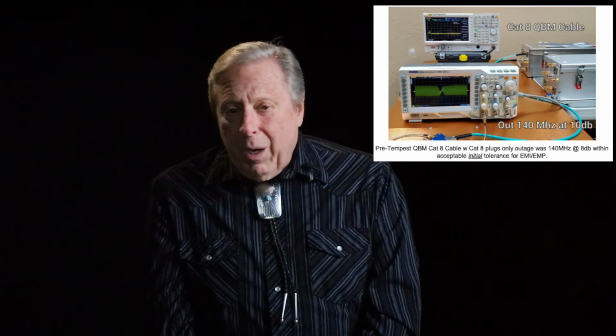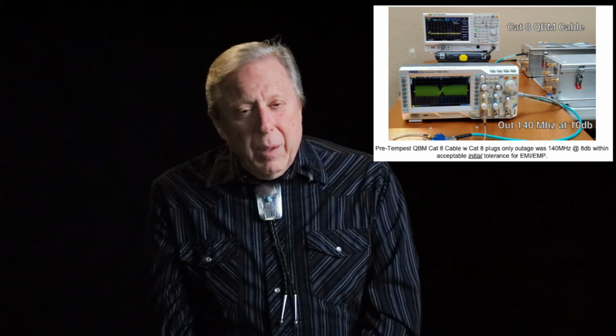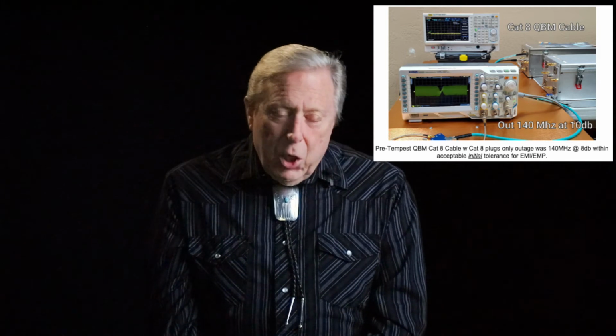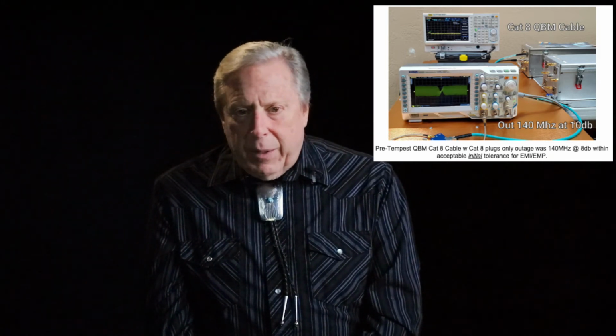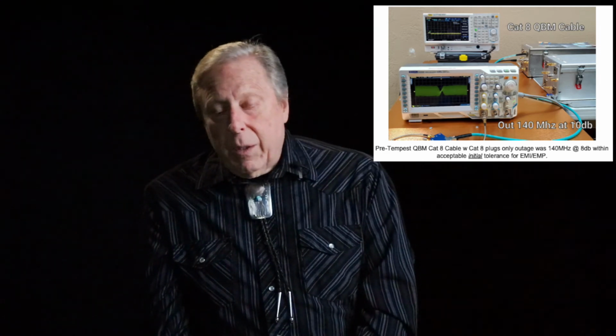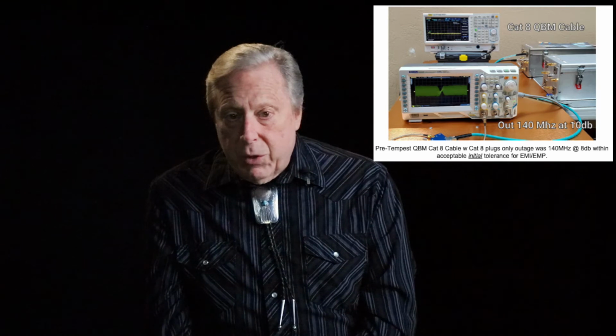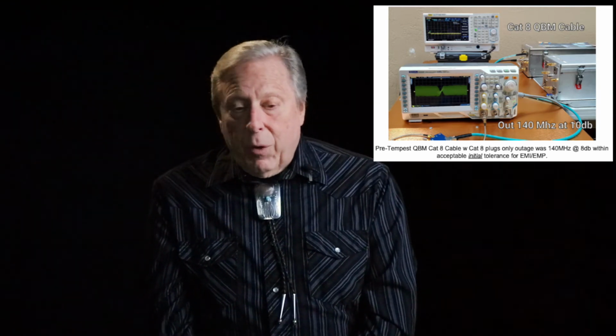The 140 megahertz being out at 10 dB again, it's so low that there's probably a good chance that it may not be affected by any of it. The better thing is if you can get it darn quiet, people can't sit outside your building and look at your keystrokes coming out of your CAT5 or CAT6 cables.